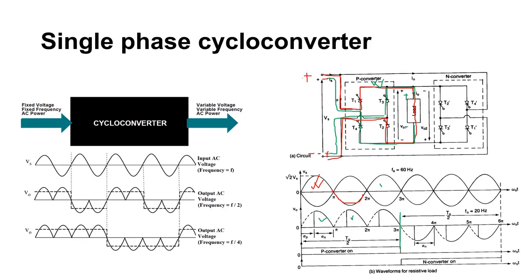So during that time, our polarity here is positive again. This is positive, this is negative. When this is positive the current flows like this, comes here and goes through T1 prime, and now it enters from the bottom end of the load and then leaves like this.